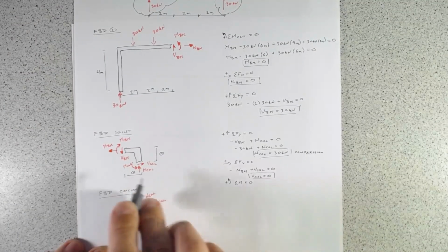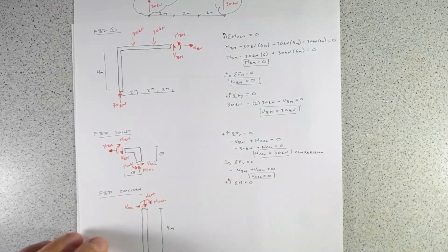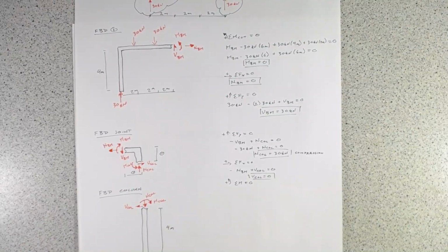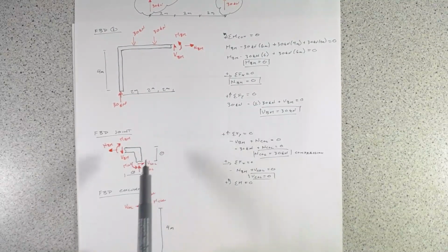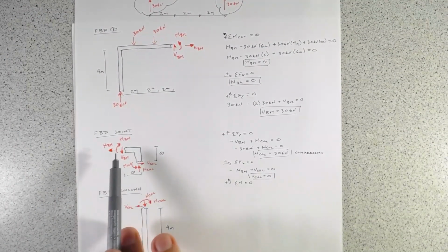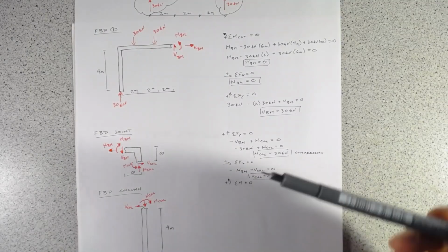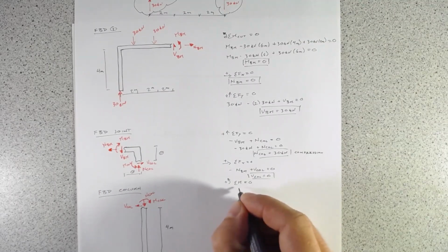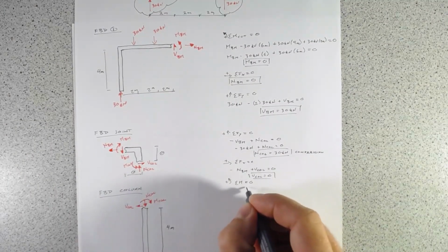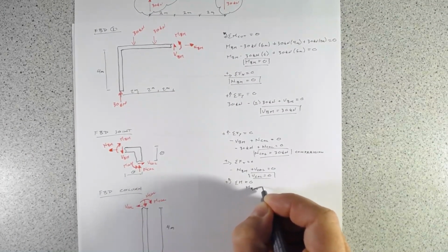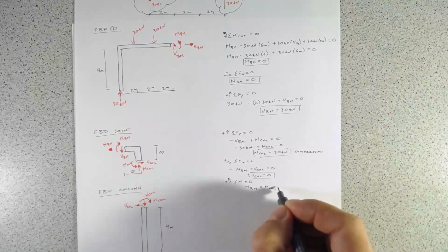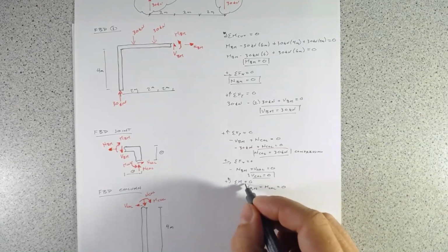You have again the orthogonal direction where we've taken this free body diagram of the joint basically at the very tip of the joint, so there's no dimensions, so all of these forces have no orthogonal distance, so it's only the moments, and we get MBM equals M column, so moment of the beam equals moment of the column equals 0.